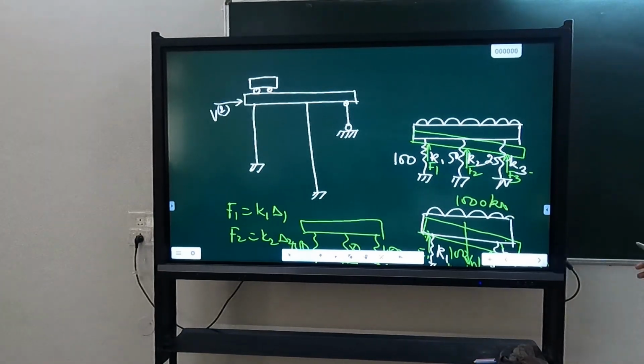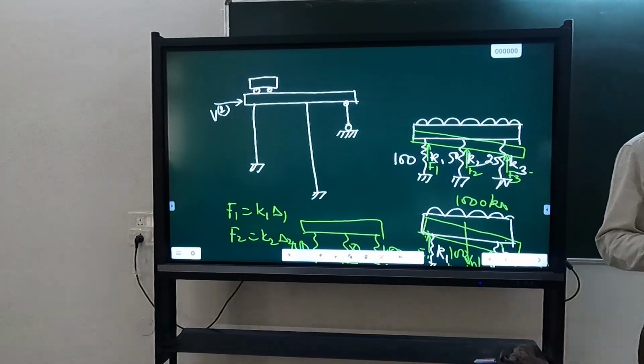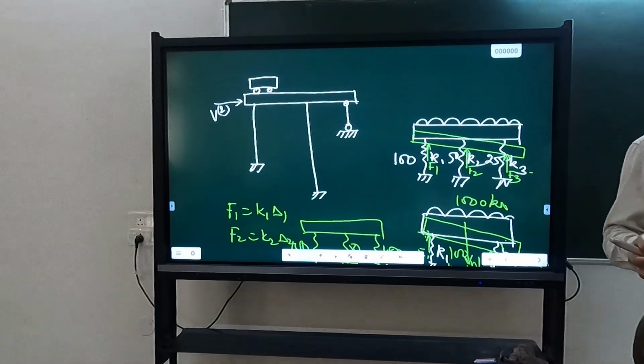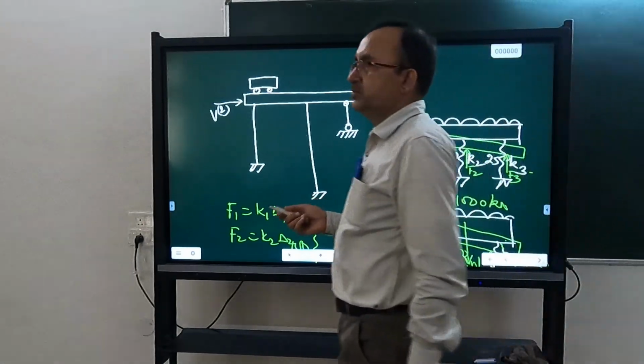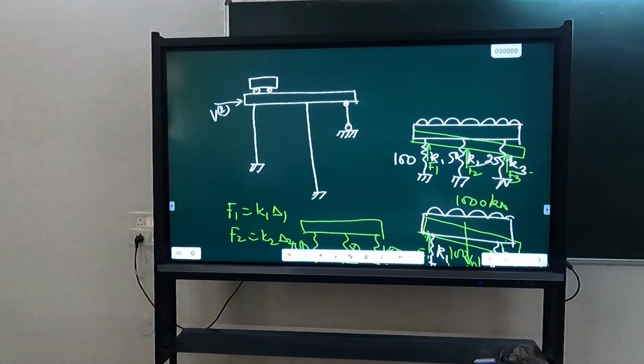And in simply supported superstructure, there is no case in which it is going to yield because moments due to earthquake are not developing. It is just moving like a mass. So the plastic hinges form, the yielding occurs in piers in case of bridges, and it is contrary to buildings. What implications it will have towards the seismic resistance of these structures? Let's say in terms of response reduction factor, what do you think?